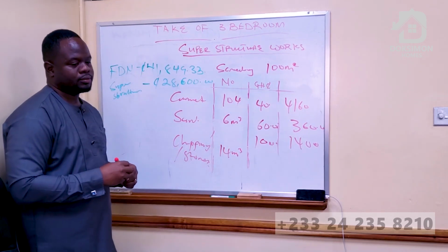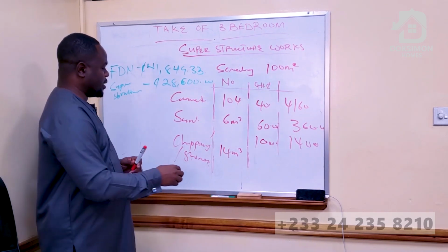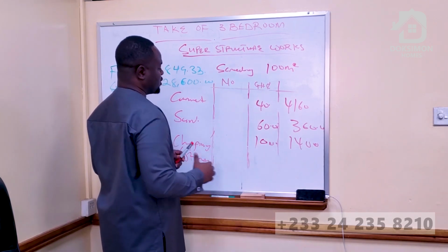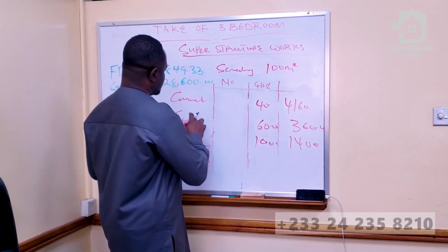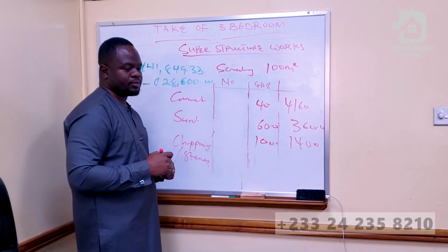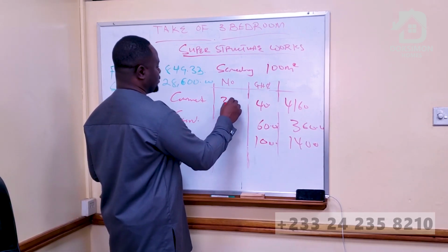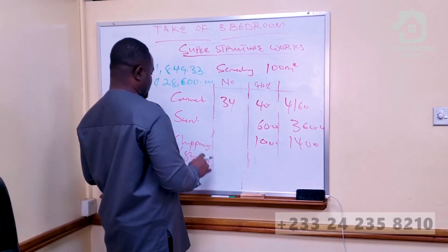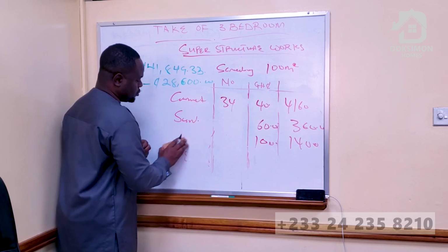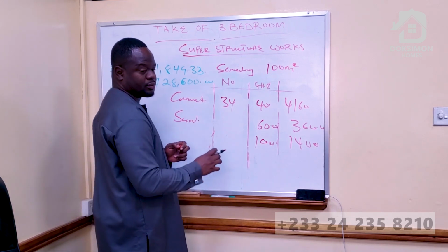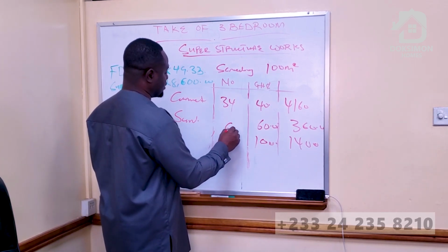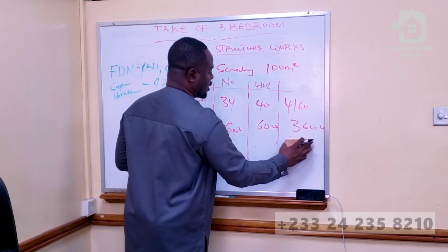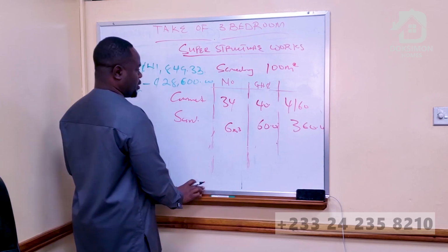If you don't have an idea, at least you should be able to know the number of bags of cement you're going to use. So with 100 square meters, you just need 34 bags for our screeding. We only need sand, which might also vary, just 6 meter cube. So it might vary every time in area.